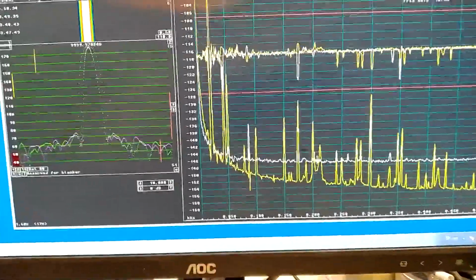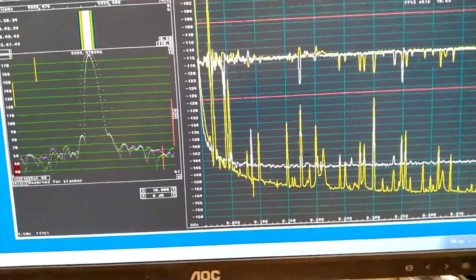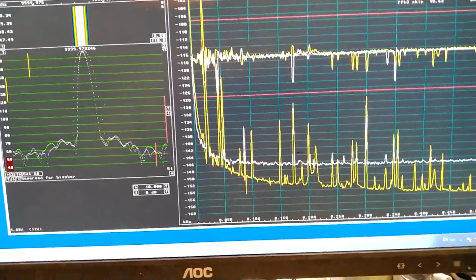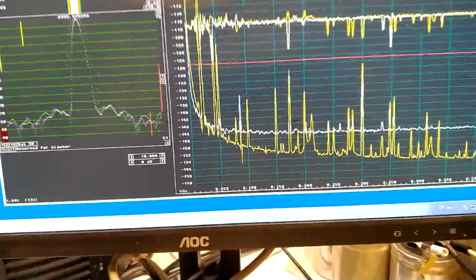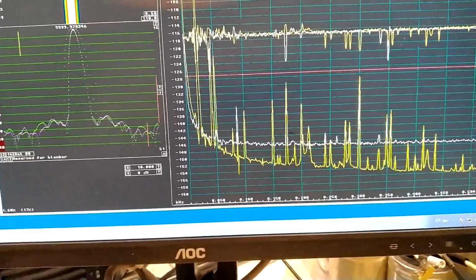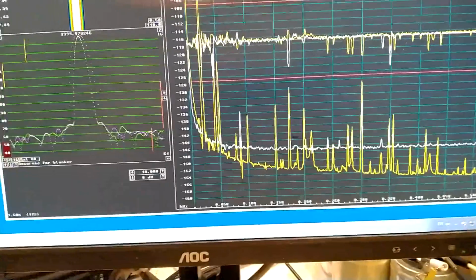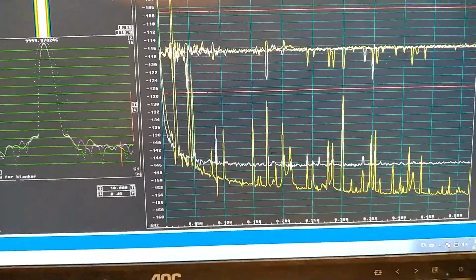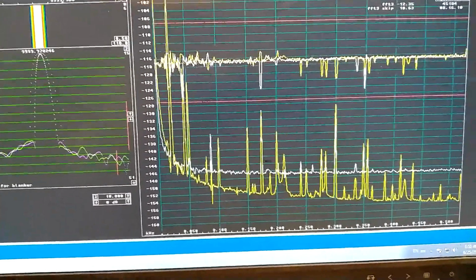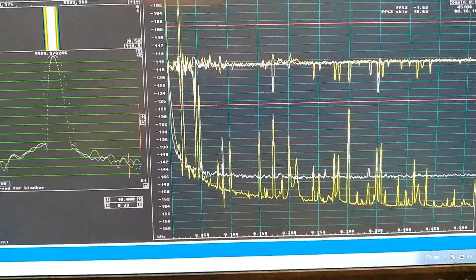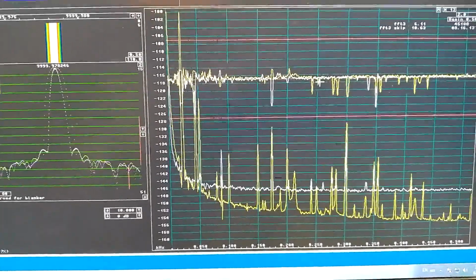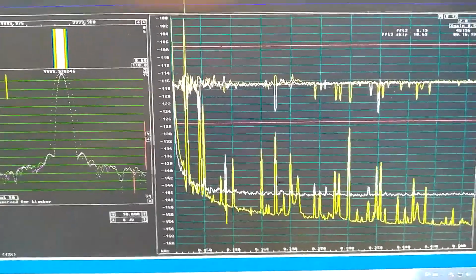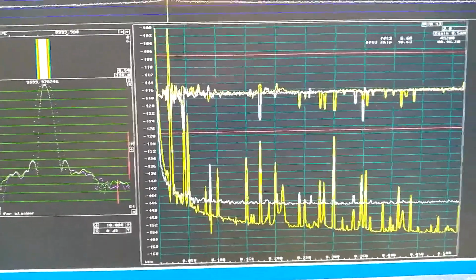The amplitude noise, on the other hand, it was about minus 150 the whole way from 100 to 400, but now it is minus 147. So it has degraded, but just a little. And normally one doesn't care about amplitude noise. Not much, at least. Correlation between amplitude and phase noise is 0, very close to 0.